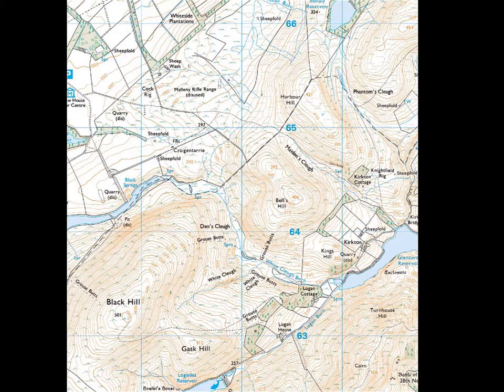In this case, we are looking at values of height or elevation. Each contour line is therefore perfectly horizontal, being a single elevation all the way along its length. Contours can of course be drawn for any kind of continuous variable, such as porosity, permeability, thickness, temperature, pressure, and so on. Contour shape and spacing tells us something about the gradient and slope of the data.